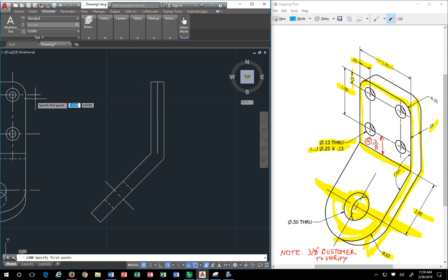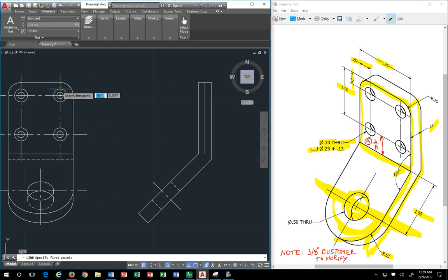And then I would reference my lines and just drag them over. See that? Use my front view to build my right side view. Remember that. Don't build from scratch. Use your views. That's how you make sure they're perfect.